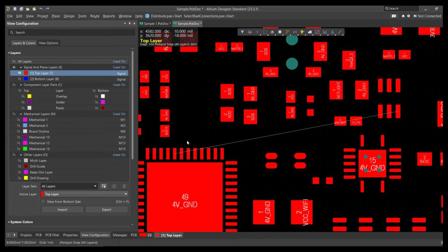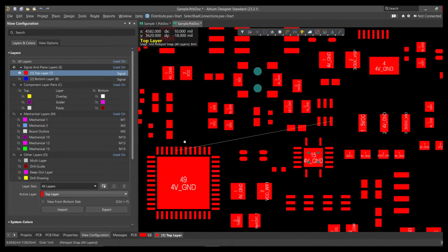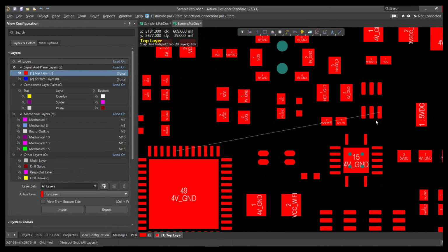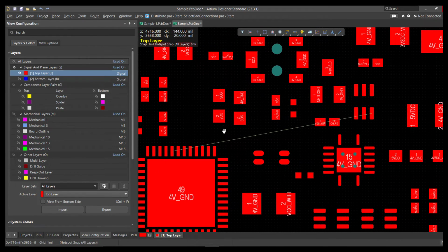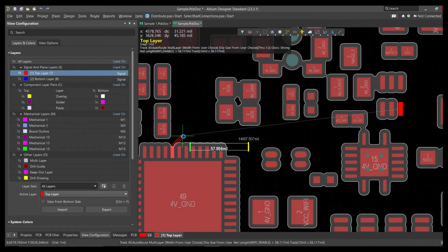In routing, there are instances when two connected points are located far apart. To simplify the routing process, activate the routing command and press the Control key. Then left-click the mouse to complete the routing between the two distant points.